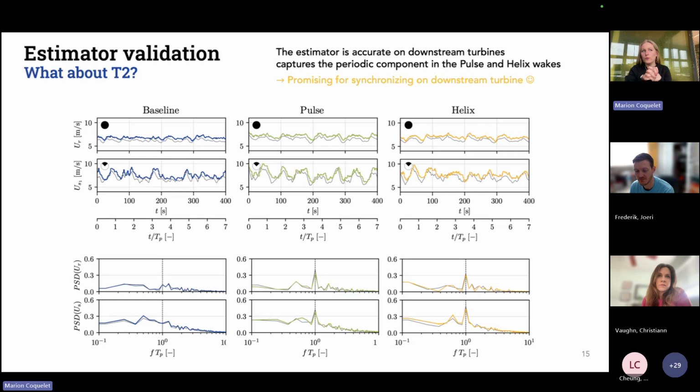Now, I believe that what we see here is also the effects of shear, so the wake is constrained and it's not just doing perfect circles. And so you see that the peak is not as high for the rotor effective as for the sector effective, but still there is a peak, and at least this is my answer to it. Okay, yeah, that makes sense. Thank you. Thanks.